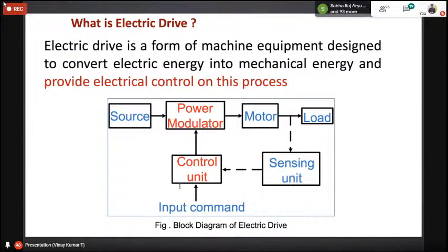All blocks' transfer functions you have to extract. Once you have the transfer function, later by using the RH criteria we can find the KP and KI range, the safe zone, the stable zone for the KP and KI values. Once you know the range, later in practical condition, by adjusting further, you need to adjust the KP and KI values to maintain error 0, right?